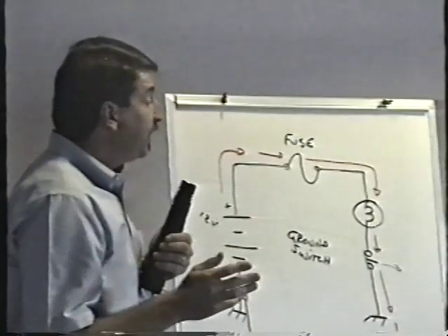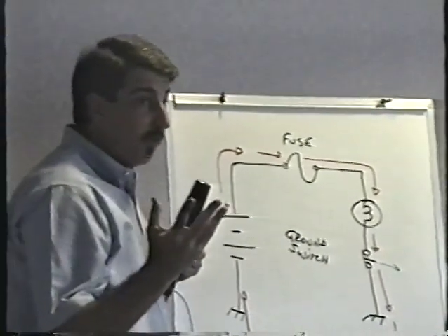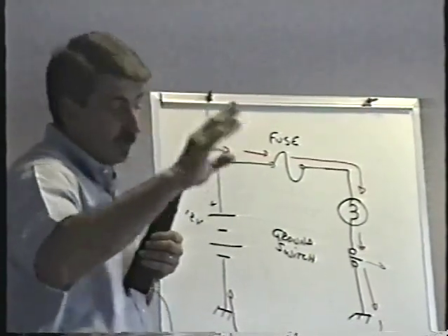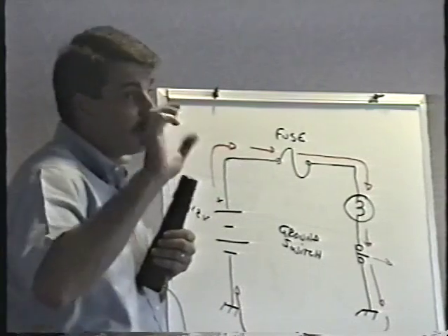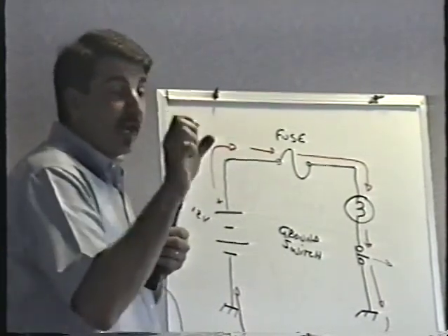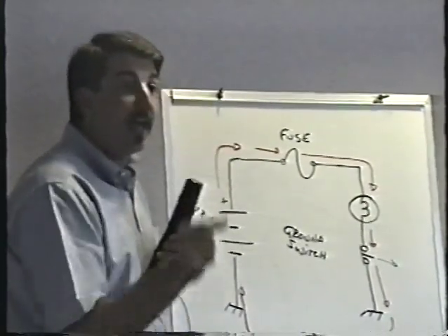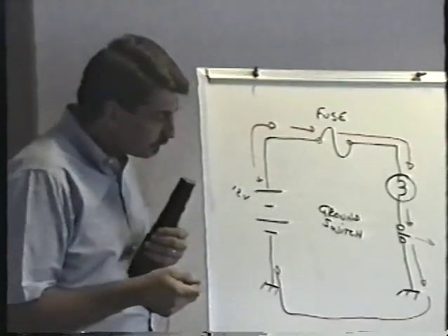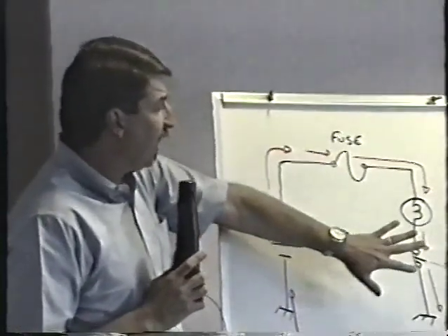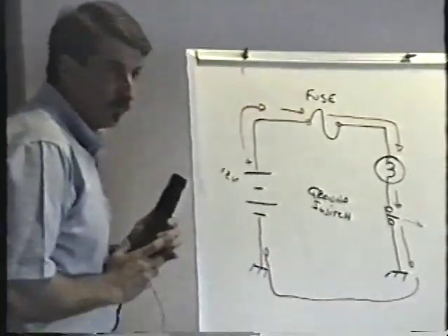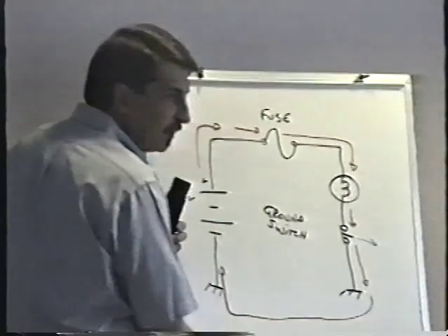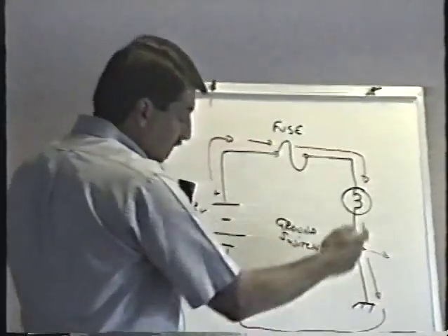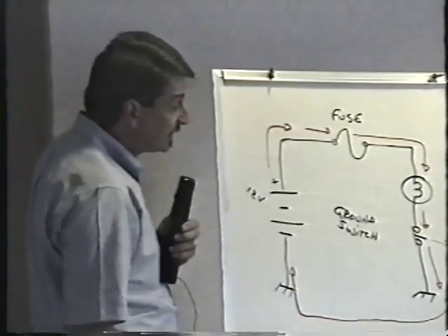In a pinball machine, to energize the coils in the pinball machine, there's always power going to the coils. Always, continuously. The whole time the game is plugged in and turned on, there's always power to the coils. To energize the coil, they ground one side of it. The ground is switched in and out. You'll see what I'm talking about later on. I'm going to show you a lot of examples of the ground switch as we go through the class. It's very common in monitors. In most circuits, instead of switching the power on and off, we switch the ground in and out instead.